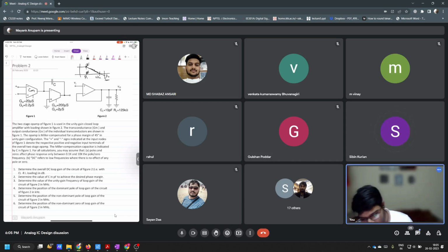What you can do is, you can also do the following. As an exercise, you put resistors here, GDS and C1 here. You also put GL and CL here. And what you can do is, you give a test voltage here and see what is the current coming out.